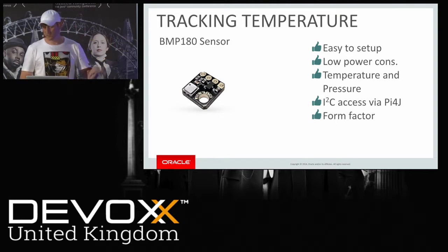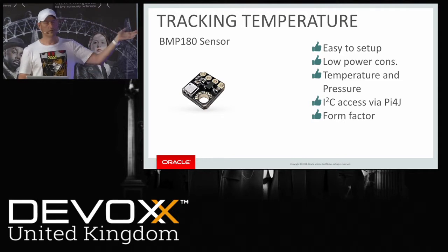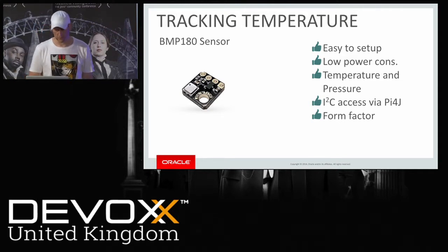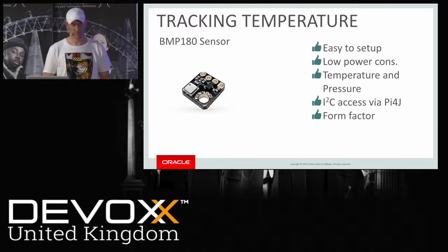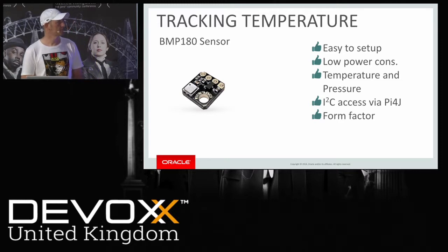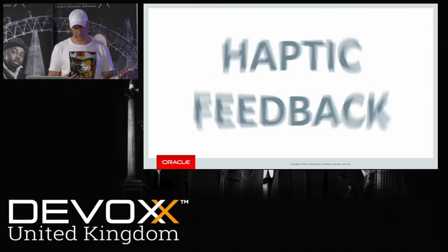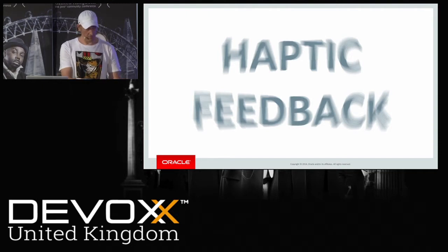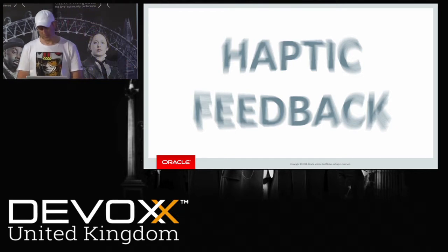So I use this one, and I don't show you the code because there's even an example. If you go to the Pi4j page, there you see an example how to access a BMP180. It's not really rocket science. That's easy. Java was not the problem, building this thing. That was easy. That was really coding. You just see, oh, I need that. Okay, code it, done, works. No problem. The problem was make it small and make it reliable. That was the real problem. And have some strategies, for example, if it's not in use, if the position doesn't change, then don't do the updates. And if you recognize, oh, it's moving, then start updating and all that. That was the bigger problem.